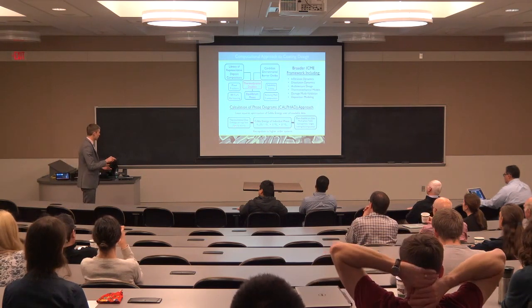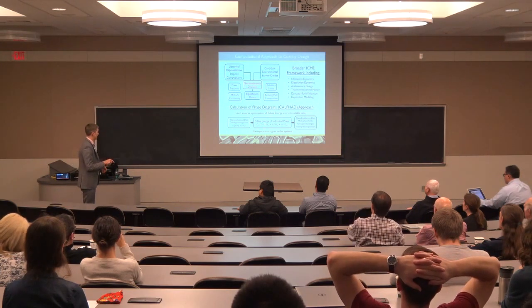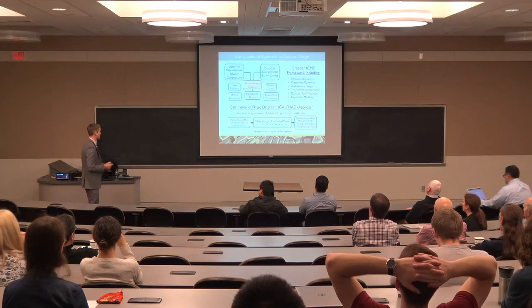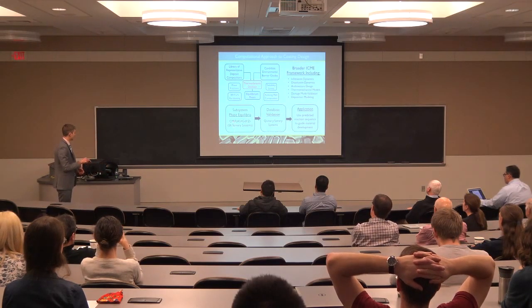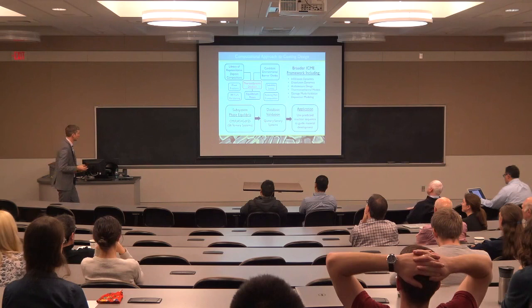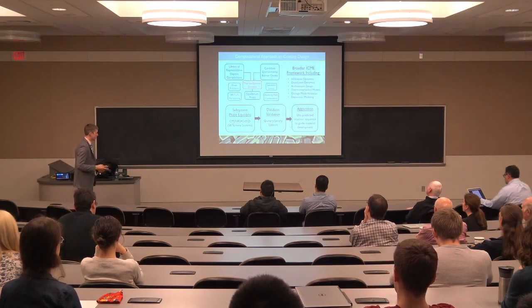And so we can use both of these types of information in a fitting approach to take a stab at understanding what the full Gibbs energy description is for a given phase. And so the process that I'll talk about today is first efforts to understand the phase equilibria in the relevant subsystems. What are the reactions that take place between these deposits and the candidate coating materials?